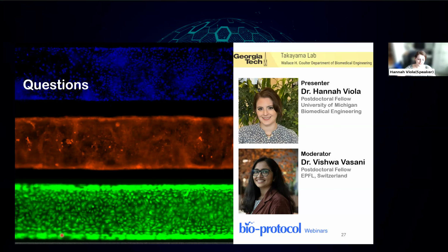But if your tool is breaking, it's an indicator you need to go back and optimize your simulation better. Ideally, the first time you do a cut, if you have a microscope camera on the tool, you want to stay for a while and watch the cut happening so that you can see what's going on. And if there happens to be a break, you might be able to see why it happened.